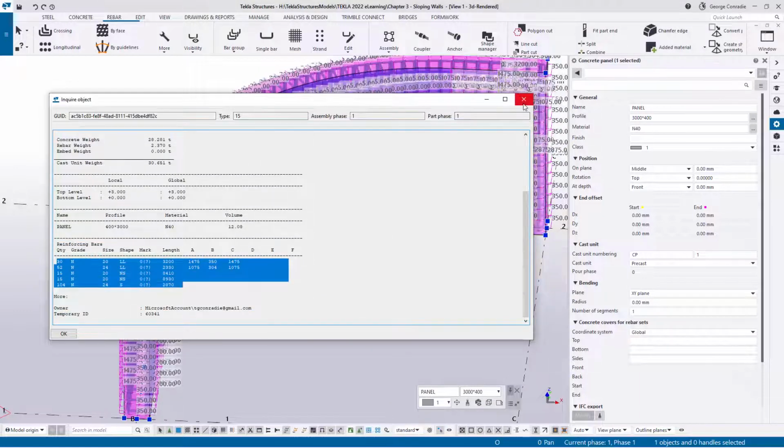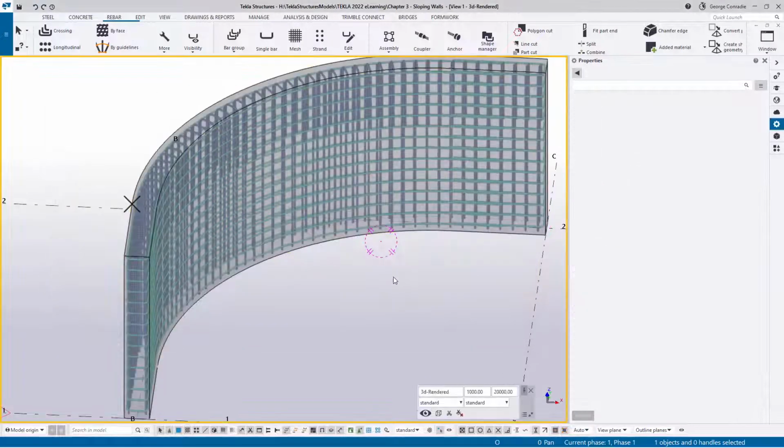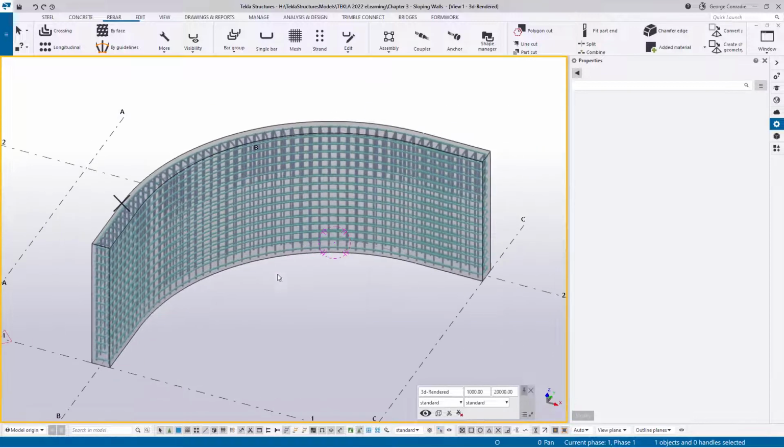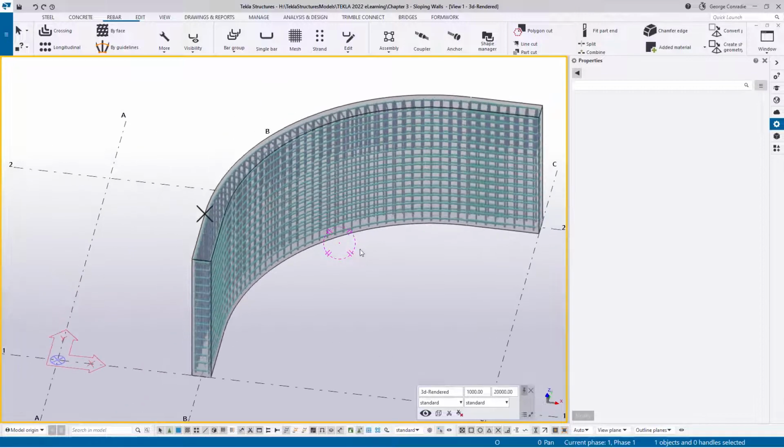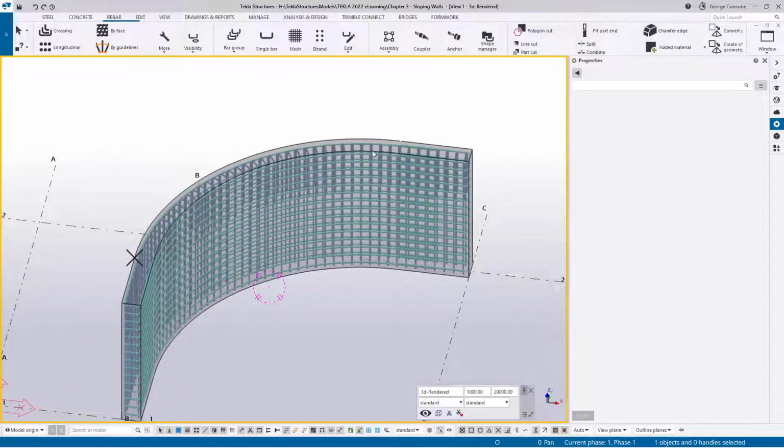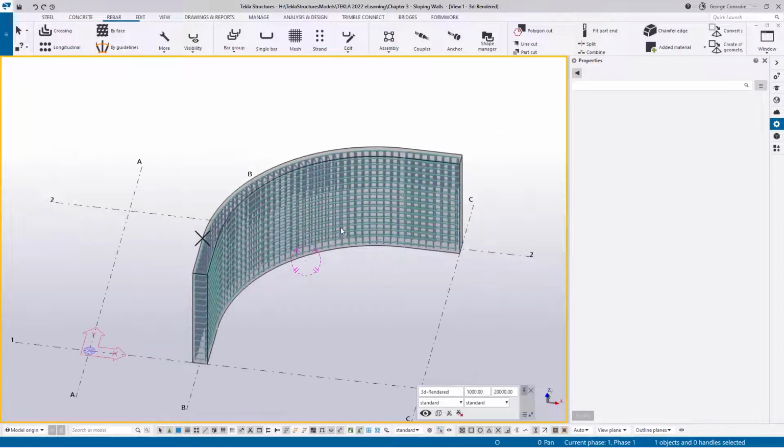So that is the way that you would approach manual detailing of curved reinforcement walls in rebar sets. It's extremely easy, it's extremely powerful, it's easy to change, and you don't always have a component to save you in a case like this. Sometimes you get a tricky concrete geometry that you need to address with manual modeling, and this is the way you would do it.